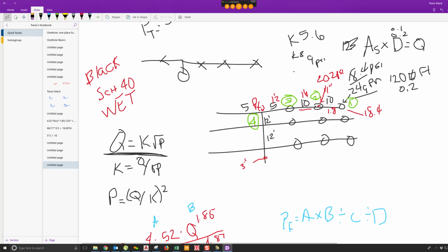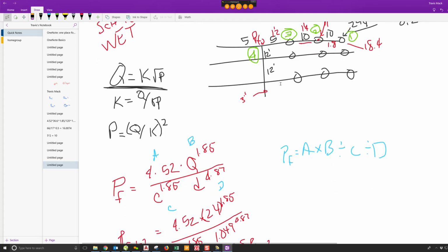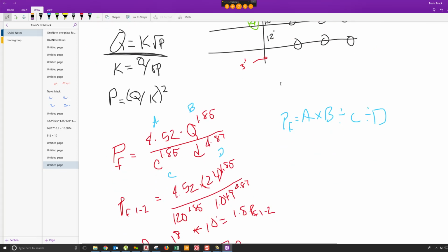So again, this is why you don't ever get a perfect theoretical 0.1 over 1500. You're never going to get 150 gallons for your system. You're always going to get something more than 150 gallons. That's just because every time you run through a piece of pipe, you've got to account for that friction and that pressure. That pressure hits the same size hole and it adds more flow to come out. Does that make sense?